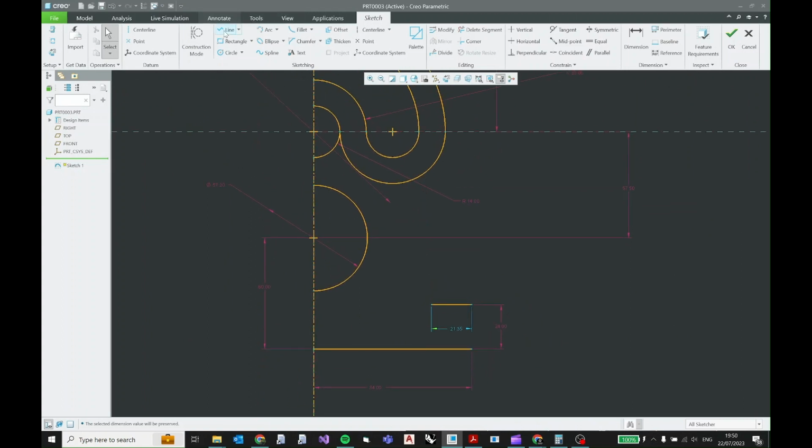So I'm going to select the line command over here, and then take any point on this circular arc and keep going down until I reach this line's height, and then press escape. Now, this point and this point: I held control and selected these two points so that I can have this horizontal dimension. It was 50, as we calculated.